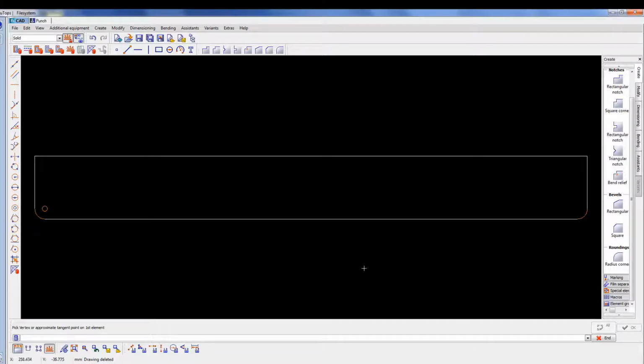because we've got Special 37, which is a 23mm rad. So I could put radius again, 23, touch it on that, and that'll turn that into a Special 37 tool with 23mm rad. For the Special 36, it's an 18mm rad. So again, radius corner 18, touch it on the corner, and that's put an 18mm rad, which is for the Special 36.